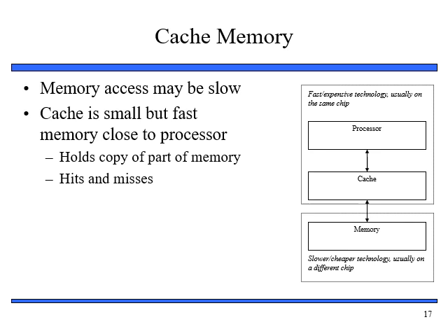Memory is slower, cheaper technology, and it is usually off chip, whereas cache is very fast and is on chip, meaning it is on the processor. What we can do is move a local copy of a portion of memory into cache. We have two types of cache. Number one is D-cache, which is data cache, and then we have I-cache, which is program cache.